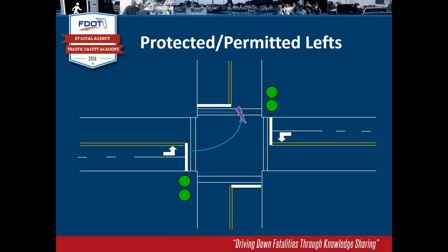And so if you have lots of pedestrians crossing, then maybe you eliminate the permitted portion of the protected permitted lefts. Again, it's one of the things you have to be aware of and thinking about as you're choosing how should my left turns operate.